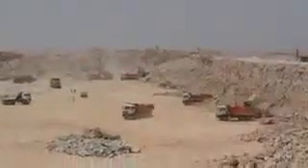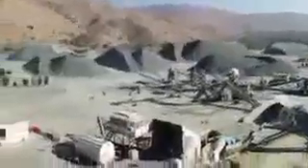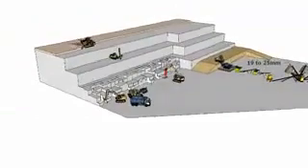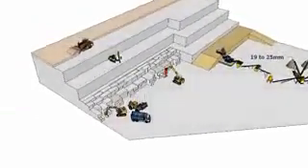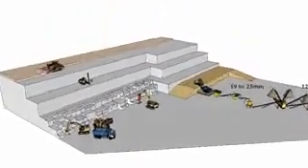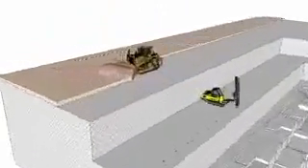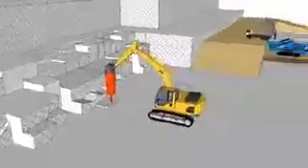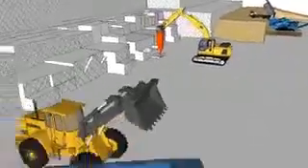Quarries and aggregates production. Rock is extracted by drilling and blasting. Blasting is used to loosen and fragment the rock so it can be loaded into tipper trucks which transport it and tip it into the primary crusher at the crushing and screening yard. Using a series of crushers and screens, connected by conveyor belts, different size ranges of aggregates are produced and then transported to the asphalt and concrete batching yards on site.